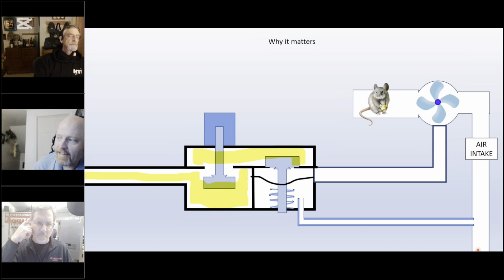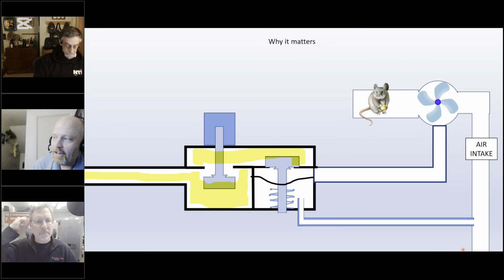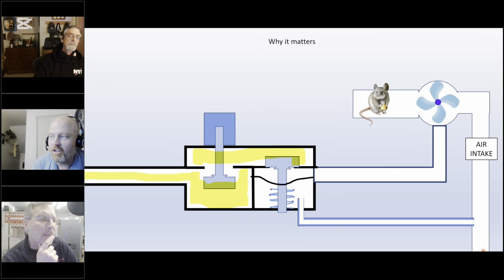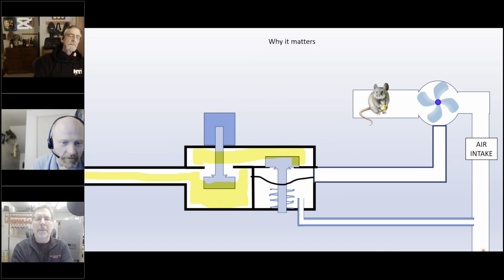And the way you would test that is if it's a TRX, you're going to do this about 4 inches above the top of the boiler. You're going to drill a very small hole in the pipe. You're going to shove your manometer tubing, about 2-3 inches of tubing, inside the pipe, run the boiler at maximum fire. And if you have negative 0.25 inches on 3-inch venting, you're fine. Anything up to a negative 1/2 inch would be perfectly normal, even if you're running 150 feet of venting.